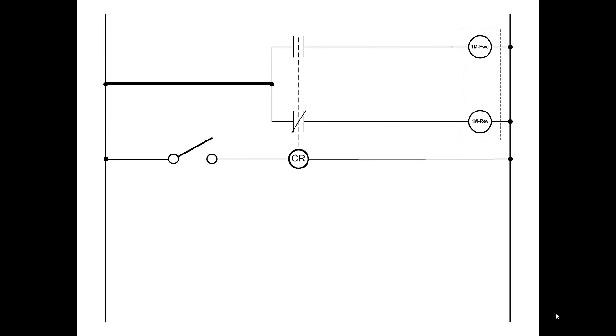This arrangement is actually worse, but at least we're going in the right direction. This is worse because the motor is always running in one direction or the other. If you look right now, the relay is de-energized, so the normally closed contact passes current flow from the pole on the left through the motor to the pole on the right.